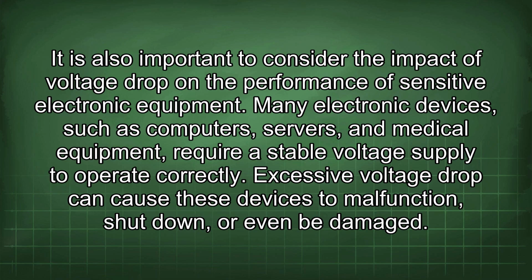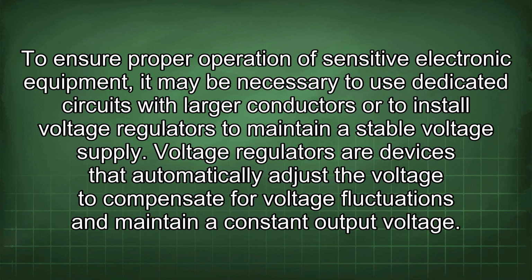It is also important to consider the impact of voltage drop on the performance of sensitive electronic equipment. Many electronic devices, such as computers, servers, and medical equipment, require a stable voltage supply to operate correctly. Excessive voltage drop can cause these devices to malfunction, shut down, or even be damaged. To ensure proper operation of sensitive electronic equipment, it may be necessary to use dedicated circuits with larger conductors or to install voltage regulators to maintain a stable voltage supply.